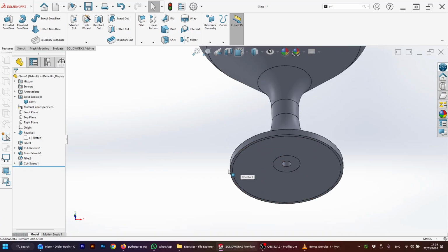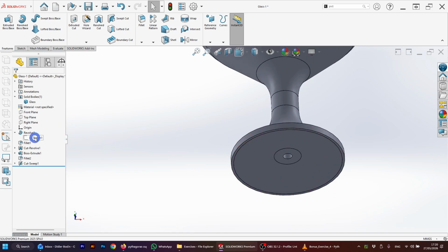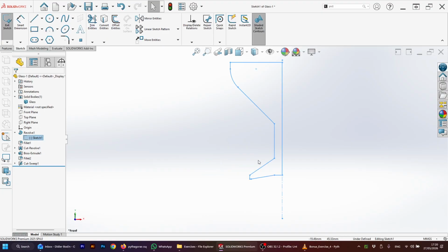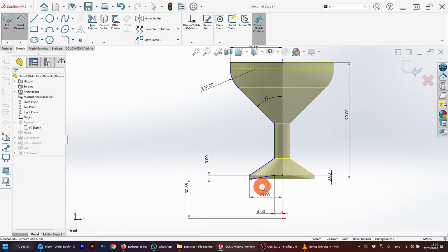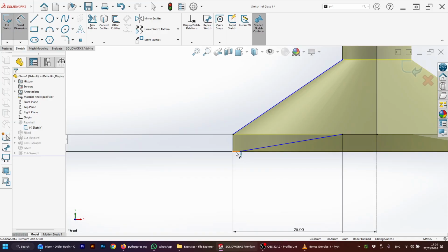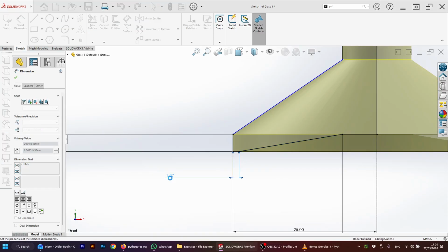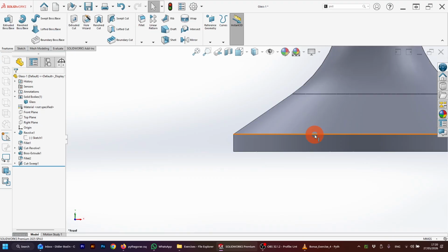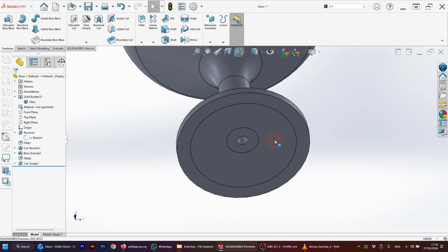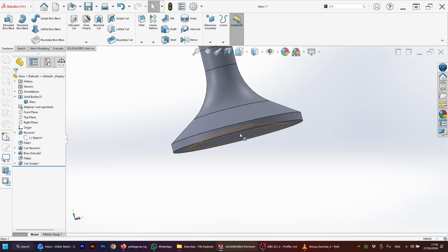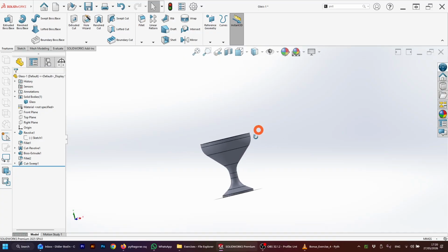Now you can see this, what used to be thin, if I go back now, actually when I did Control Z, I can't go back. It's not allowing me to go back to reapply what I just did. So be careful with Control Z. I edit, and I would just make a smart dimension, telling it that this little line is actually 5. Approved. So now I have the base, I have the negative space inside, and I finish with this.